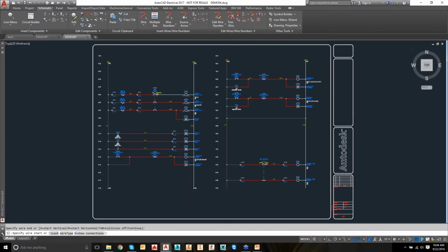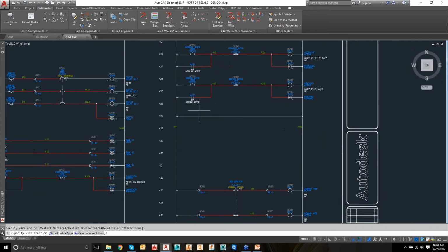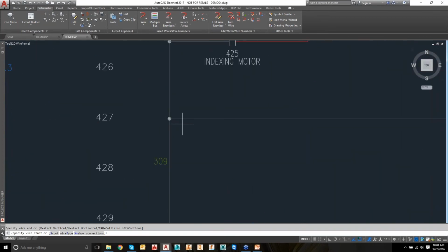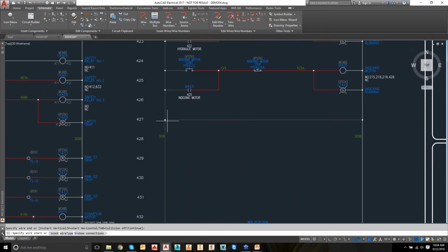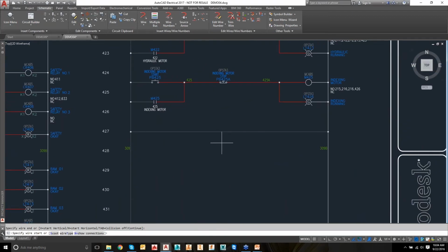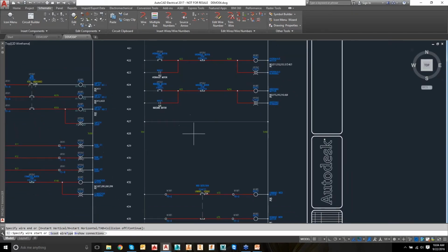What you're going to do with most controls is you need to have the ability to put in wires. Putting in a wire is very simple. You come up here, select the Insert Wire command, and then it's just a matter of selecting your connection points of where you want your wire to go in at. Very simple, just like so. Drag and drop your wires in. Notice I didn't have to be right on the connection point, and it automatically made my connections for me, and it automatically put in these nice connection dots for me. This is, of course, configurable, so if you don't want a connection dot, there are some other options, angled markers and things like that, that we are able to do as well.